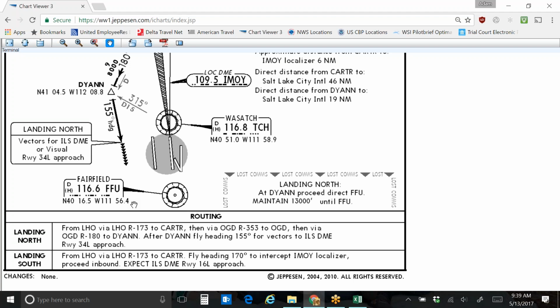not sure if anybody's ever seen how a flight pattern is supposed to work. If you take an airport with a single runway, the traffic pattern is what it's called. As somebody is approaching the runway to land, descending in, coming right at the runway, that's their final approach leg. If you go out to the turn that they make before they turn onto the final approach, that is called their base turn. And the leg that, in this case, this path over here that goes right along the side of the airport, parallel to the airport, to where you see it out your left-hand side of the airplane, this is called your base leg.